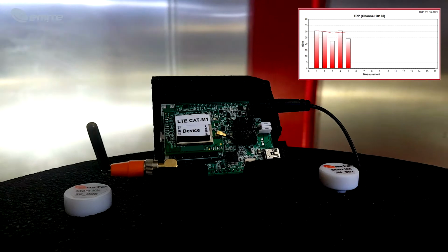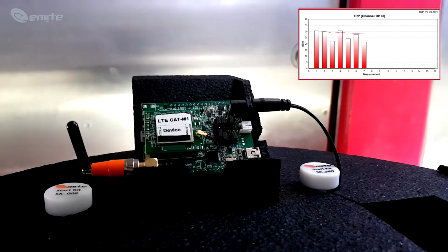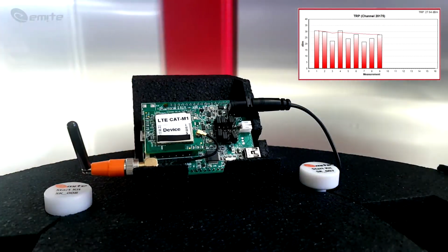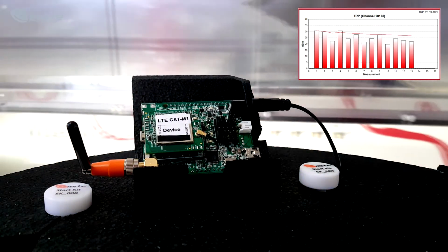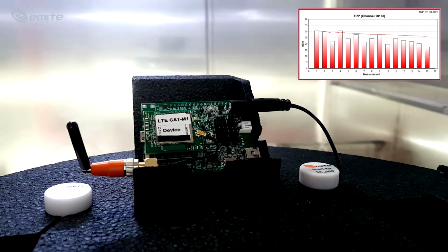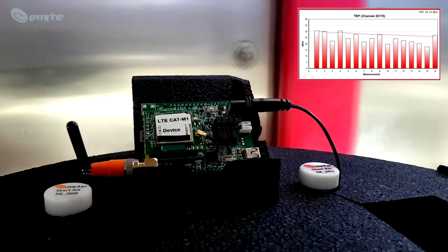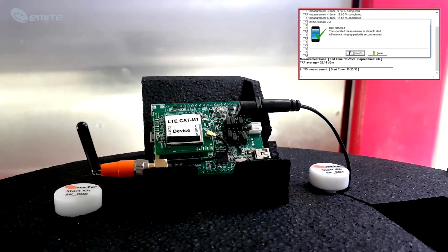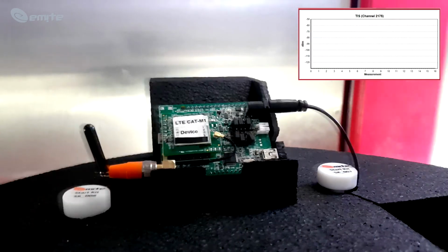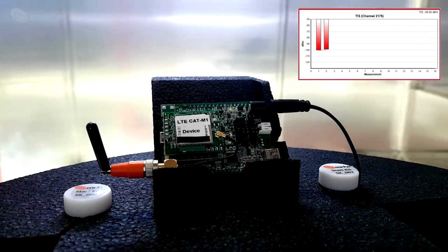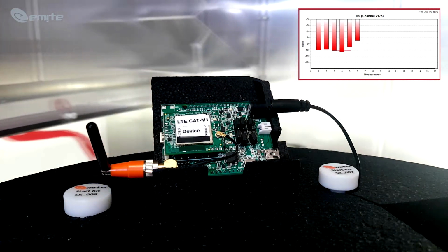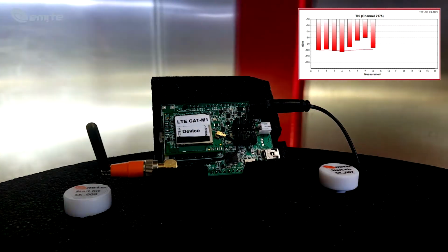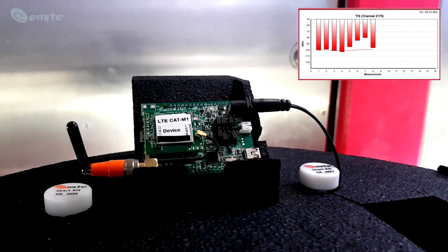During the measurements, both the turntable and the steerers move in order to improve repeatability. After finishing a test and a warming up period, the test system will automatically start the next test in the batch. The video shows an automatic change from TRP to TIS. Handover, call drop and network attachment are automatically controlled by smart GUI software routines, so that different figures of merit, bands and standards can be placed in the same batch.